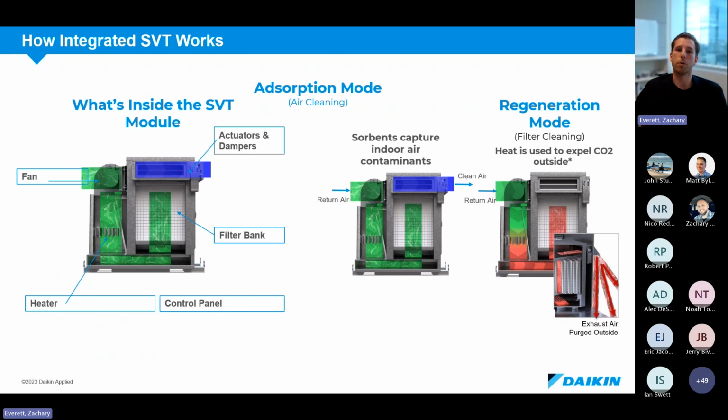The onboard controller opens your outdoor air damper, and during this regenerative mode, we have about 300 CFM of air passing through the unit itself. So as our rules of thumb and takeaways: in the regenerative mode, we have 300 CFM passing through the unit. That's being expelled, so you shouldn't have pressurization concerns. In our standard operation, we have 1,000 CFM of air, and the equivalent outdoor air is about 2,000 CFM.